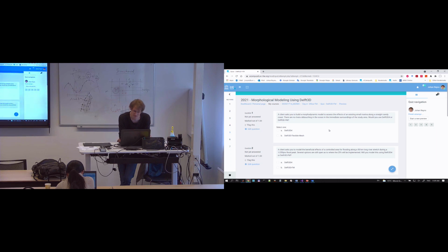Less expensive. Well, the marina is existing, so there's probably no design change, so you can make one grid. There are also no rivers, so you don't expect 3D effects, density gradients, this sort of stuff. So you don't need 2D-3D coupled models or whatever. You can do with a simple 2D model, and then probably Delft3D4 is faster. So I would choose Delft3D4 in this case.